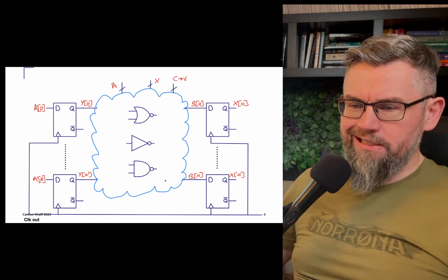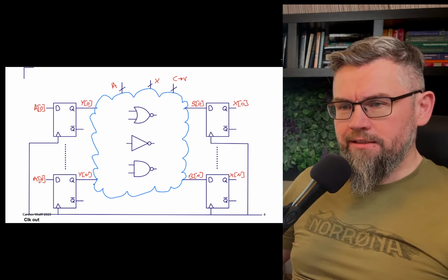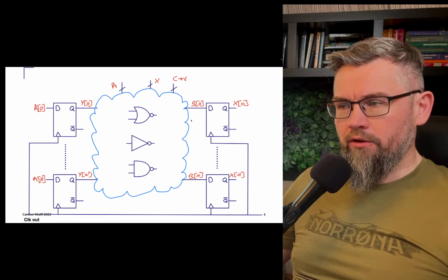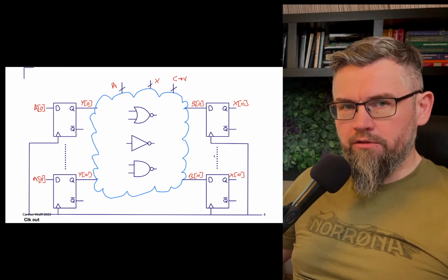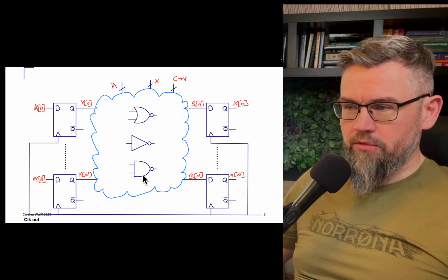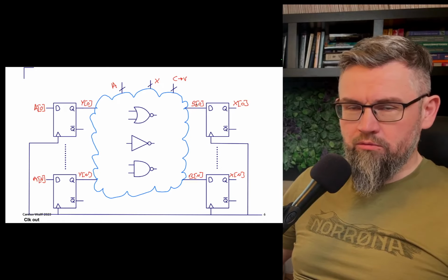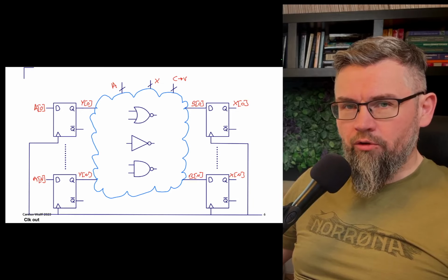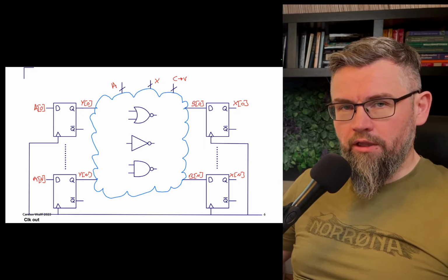The whole idea is that the data coming in, so the B in this case, only needs to be correct when the clock strikes. So as long as, well, it can transition, the B can go 0, 1, 0, 0, 0, 1, and so on. As long as it's correct when the clock strikes, then the system will work.